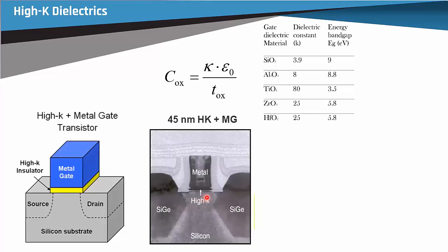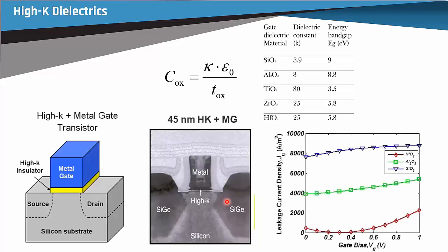So really in 45 nanometers at Intel, they started using high K metal gate. And I think in TSMC it was at 28, maybe at 45 as well. And we get a lot reduced leakage. So we did something really crazy: we took the silicon dioxide out of the CMOS process, which was the basis of the CMOS process, but it worked, and that's what we're still doing now, as we'll see next week.